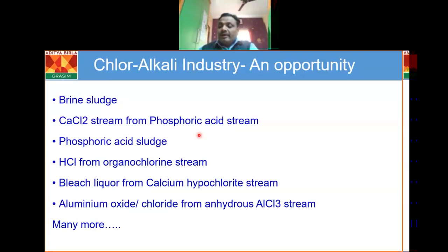There was about 100 to 150 ppm of organic residue, and we adsorbed this residue on a specialized adsorbent, and the quality of HCl is as good as virgin HCl and has added value. Earlier, this HCl had a negative value, around 2000 to 3000 per ton. Now it is a positive value of 4000 to 6000.